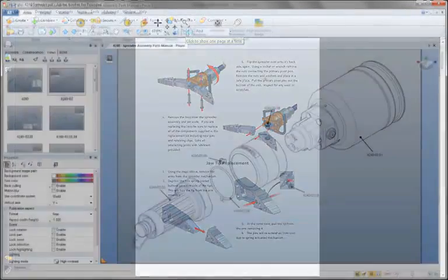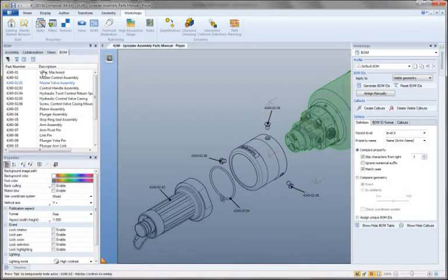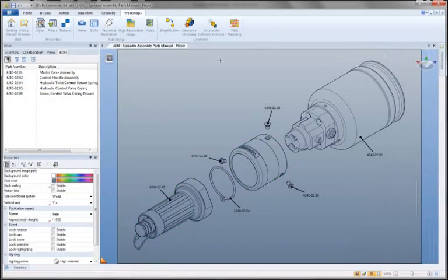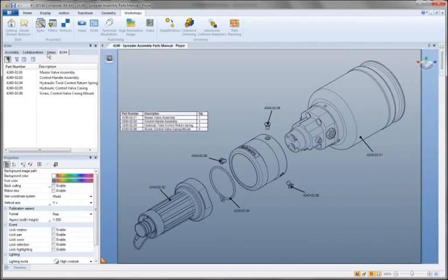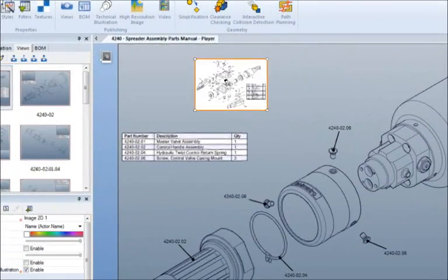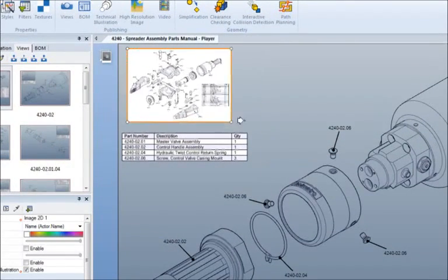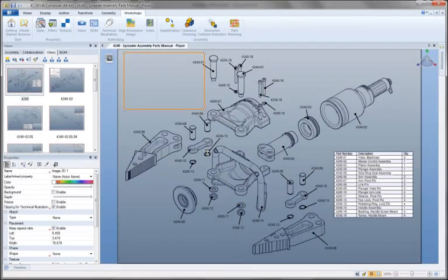It should be noted, however, that with 3D via Composer, we can take technical communications beyond traditional formats and create compelling interactive experiences. In the case of an online parts manual, we utilize 3D via Composer's intelligence to include an interactive bill of materials. We can hyperlink components and create dynamic panels. For example, to return a user to the top-level assembly view, we can utilize a small image as a virtual back button. Navigation is aided by rich graphical content.